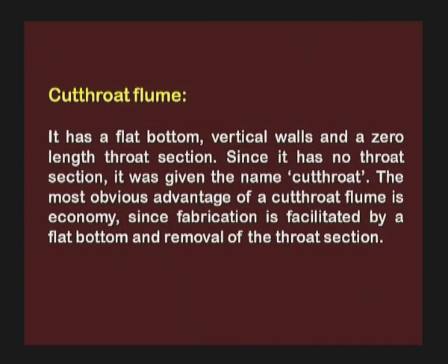Cut throat flume. It has a flat bottom, vertical walls and a zero length throat section. Since it has no throat section, it was given the name cut throat. The most obvious advantage of a cut throat flume is economy, since fabrication is facilitated by a flat bottom and removal of the throat section.